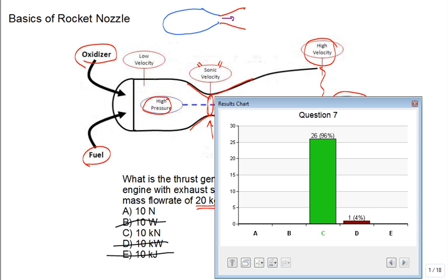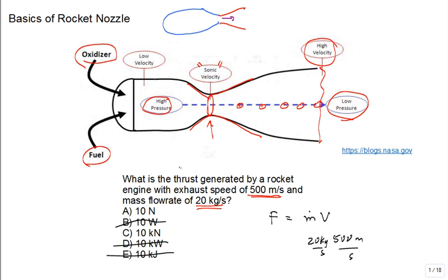True? True. What is thrust? Force, a force. Okay. So what we would like to do to improve the thrust of a rocket, and that's why they make them this way, is if this can come out really, really fast, faster than the speed of sound at that temperature for that gas, it's great for thrust. See? So you would want this velocity greater than c going out. But that means it's a supersonic nozzle, not a subsonic nozzle.